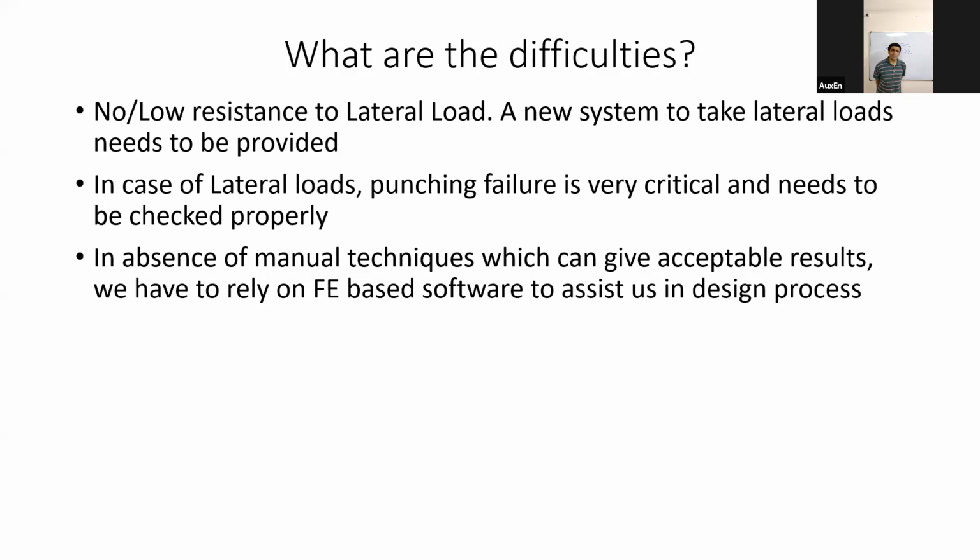Now, even if you are providing a lateral load resisting system in the form of shear walls, let's say you have provided good shear walls and everything, still when your flat slab building takes earthquake load, what will happen? Your punching effect becomes even more critical.